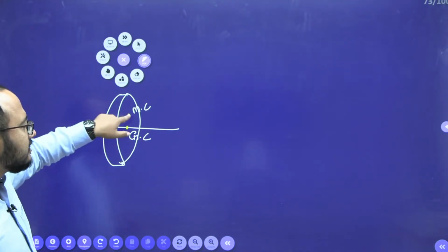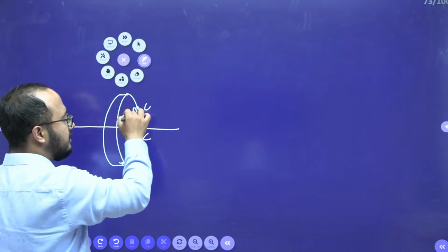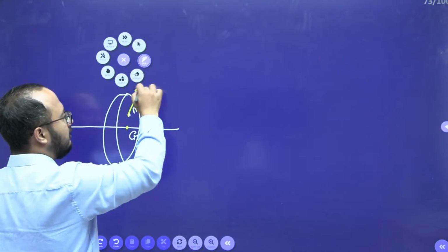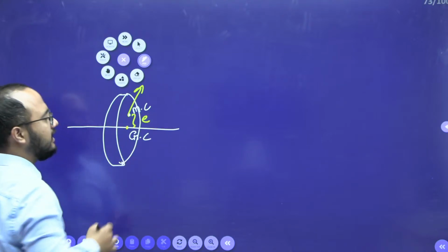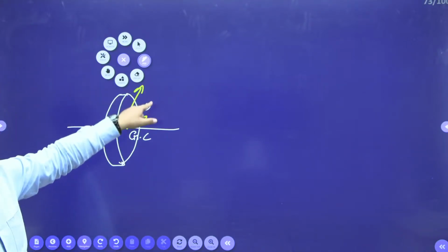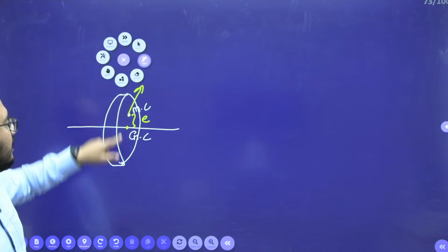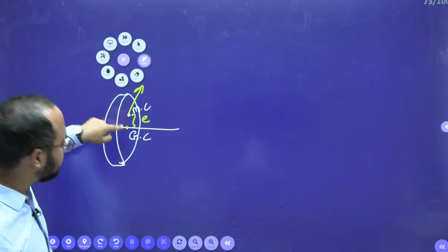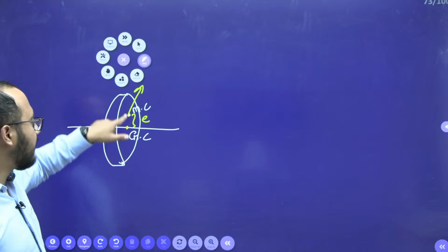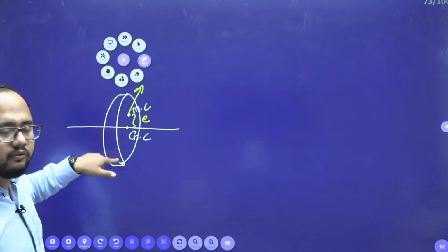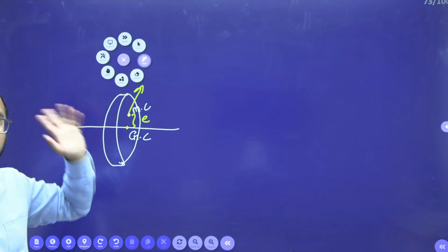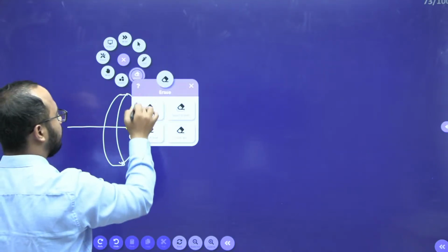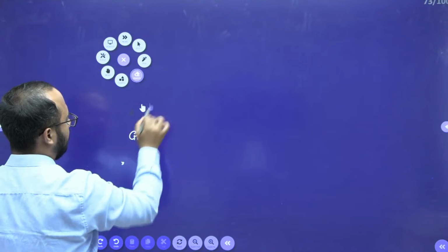If the mass center is here, obviously the resultant force will be acting here itself. So because of this eccentricity, you will have the disturbing force. Otherwise, it will not have the disturbing force. If the mass center is at the axis of rotation, there will not be any disturbing force, and there will not be any problem of vibration also, right? I hope this is clear.